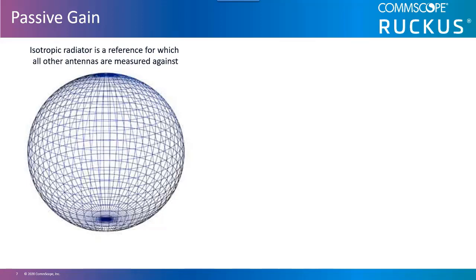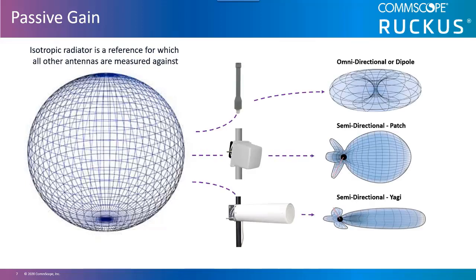As you learn in the RF math module, dBi is decibels referenced against an isotropic radiator. In antenna terms, dBi is the term used to reference the amount of gain displayed by real-world antennas compared to an isotropic radiator. Antennas, in addition to placing signals in the air, receiving signals, and shaping coverage, also passively amplify RF signals. This means that they increase the gain of a transmitted or received signal without adding any additional electric current to the signal the way an active amplifier would.